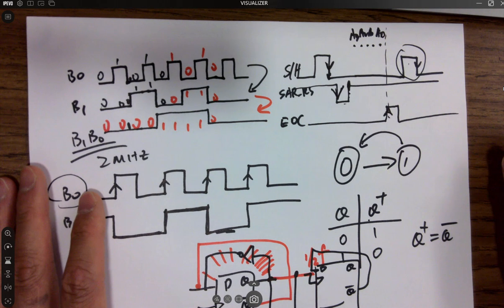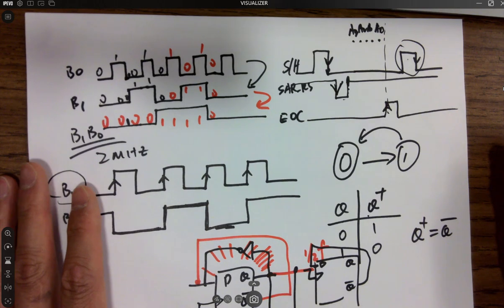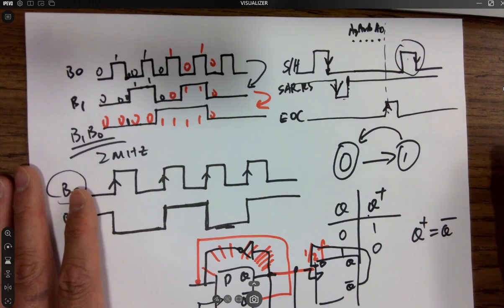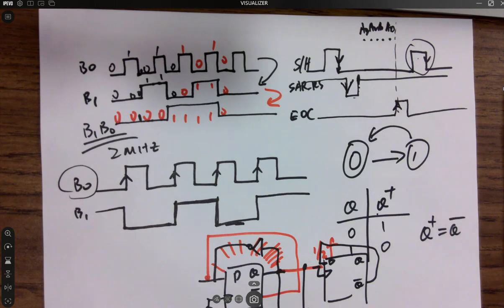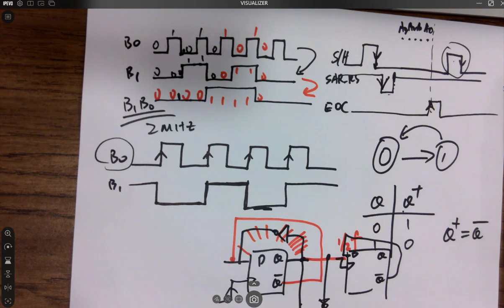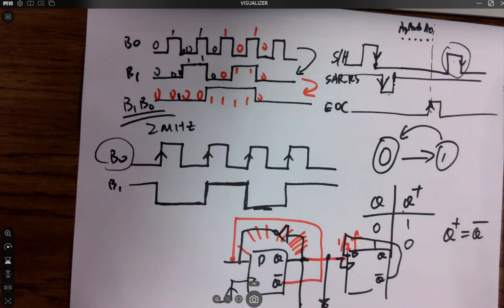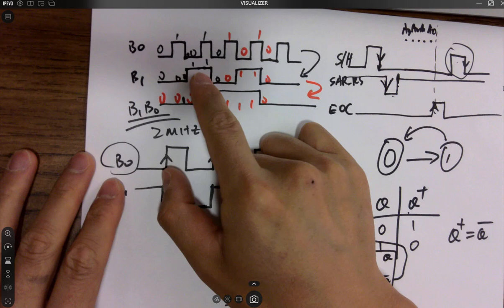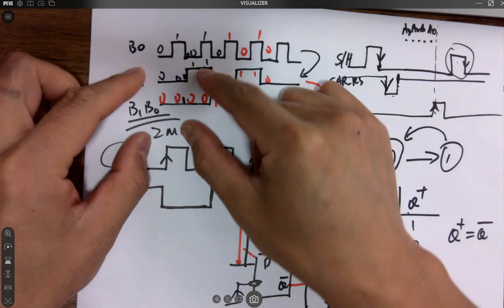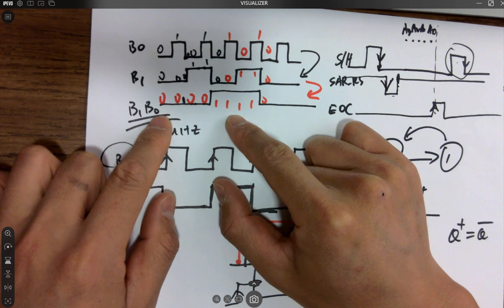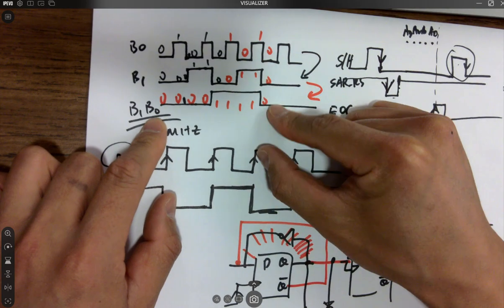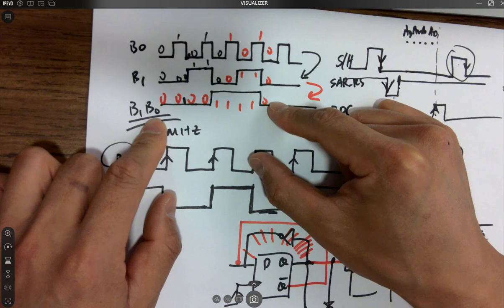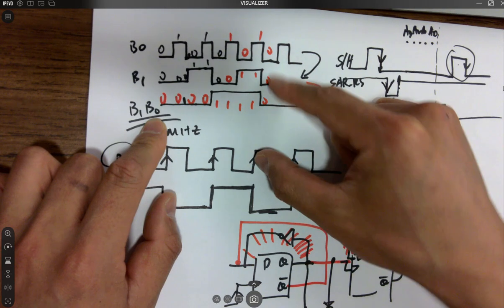So what else we have to do? That's a counter thing. So the counter: if you have a 4 D flip-flop counter, if you do not set a value to it, if you do not control it, it will count. If you have a counter like this, if you don't control it, it will count until what? Until it reaches its maximum. Until 7, right? See? 7. And then it overflows, right? It becomes all zeros. You don't need to set or reset, it becomes zeros by itself.